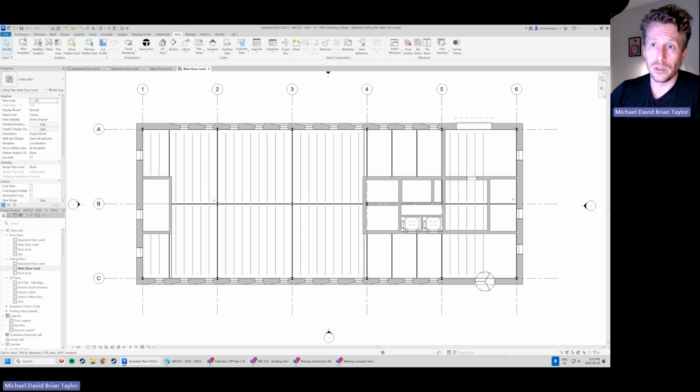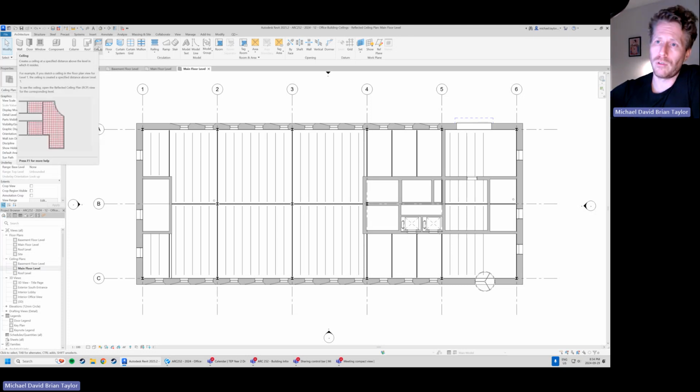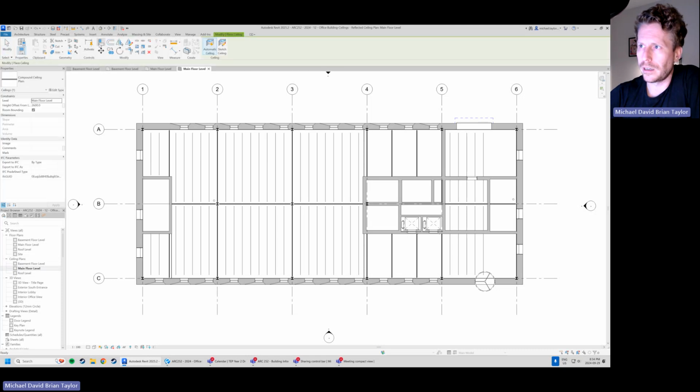We're going to jump over to the ribbon for architecture, so the Architecture ribbon. Click that, and we've got all our tools, right? Just like anything within Revit, what we need to do is get to the ceiling tool. You guessed it. The ceiling tool over here inside the Build panel. Why don't we just click that and see what we get. If I hover over for a second, it's going to show me how we use the ceiling tool. Click that, and then we're going to get a couple options. We'll just go through those. So let's just click ceiling here.